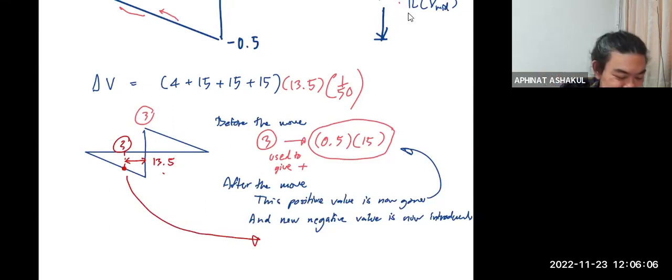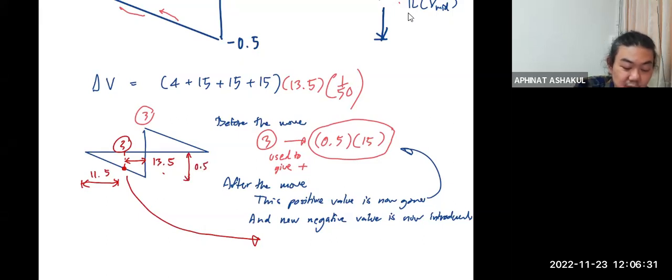Okay. All right. So 25 minus 13.5, how much is that? That's 11.5, am I right? The distance is not very realistic. You can draw it, you can write better. So that's 11.5 to 25. The height is 0.5. So the new ordinate is 0.5 multiplied by 11.5 over 25. That's the new height. And then multiply by the load itself, which is 50.